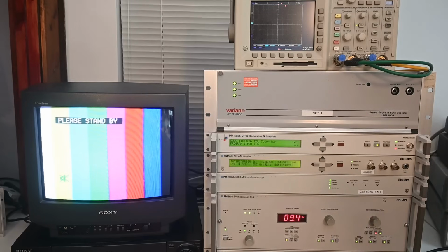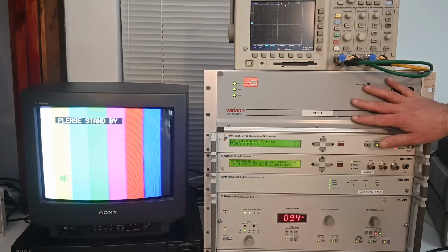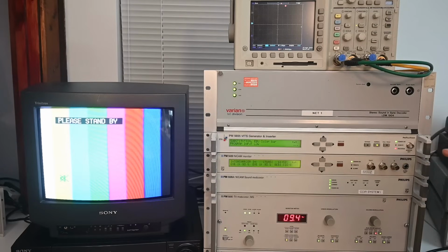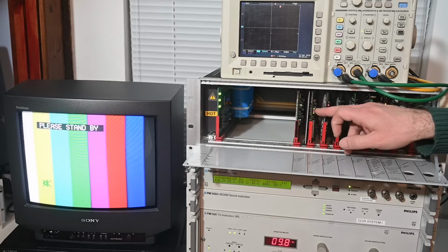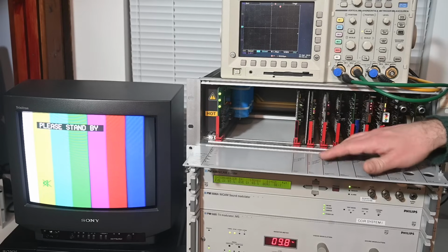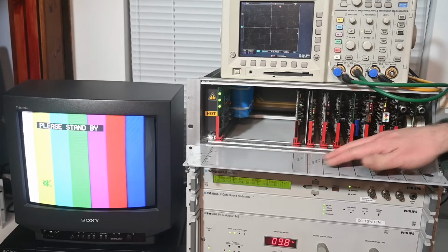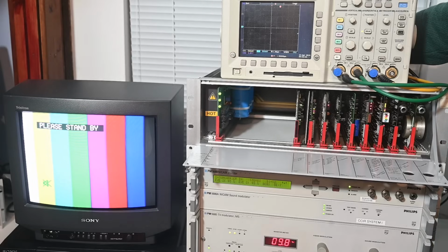Okay, so our pretend transmitter is now powered on, but with the SIS decoder this time. And another piece of equipment I've added is the 5655, and I just put that there because it's nice to have something to generate a standby signal, because presently this is not actually connected to our pretend studio. So just as before, we're starting off in the disconnected state, and we can see we have a whole bunch of warning LEDs on here, these three being the most specific, and these are indicating that we have no input. So let's plug in the input from our pretend studio.